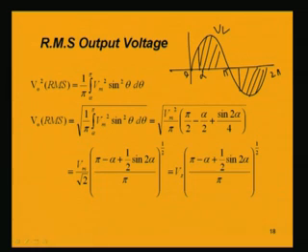So, when finding out the root mean square value, we will be using the consideration that we are finding out from alpha to pi, and the integration of Vm square sin square theta, because here it is the same shape of Vm sin theta, this is the voltage. So, we will be getting Vm square sin square theta d theta multiplied by 1 by pi. So, this is the V naught square RMS, and in order to find out the root mean square, we have to take the square root. So, square root of this whole thing.